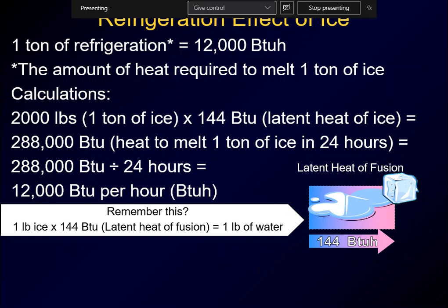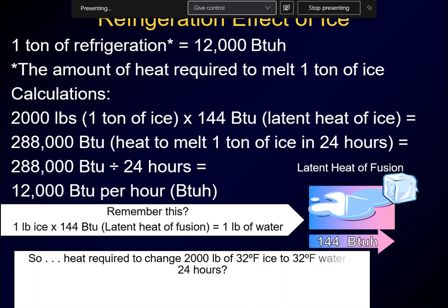You don't really have a lot of 12,000 BTU systems out there, but in split systems, residential split systems, you could have 18,000, 24, 30, 36, 42, 48, and then for some reason it skips 4.5 ton usually and goes straight to 5, which is 60,000. That's kind of the residential spectrum. So residential stuff usually stops at 5 ton, and then beyond that it becomes more commercial. But you could have systems in commercial buildings that are hundreds, if not thousands, of tons. So that stuff gets pretty big. So that's where that comes from. So if you ever wonder what that term was, there you go.